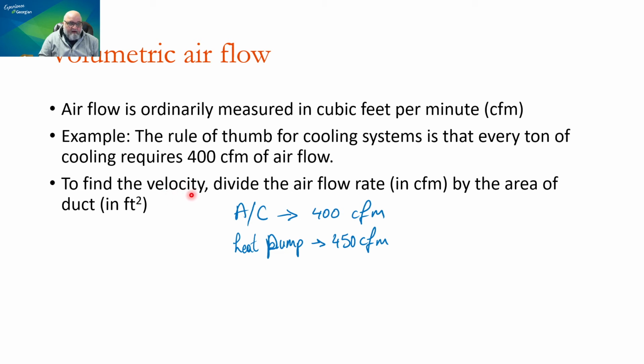If you have high velocity, you have high noise. That applies not only to airflow, but it also applies to water flow, to refrigerant flow, and everything like that. But what we care about here is the velocity of air going through a ductwork, okay? And that velocity in many cases should not exceed 650 to 750 to not create noise or discomfort.